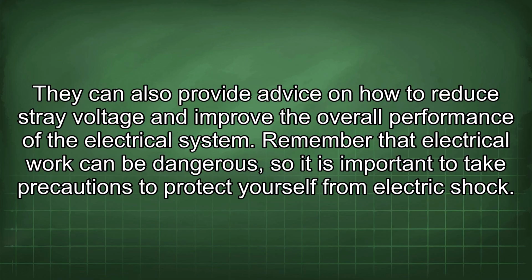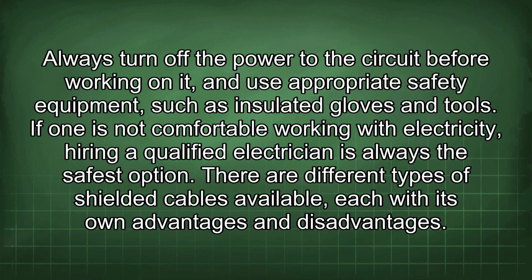Remember that electrical work can be dangerous, so it is important to take precautions to protect yourself from electric shock. Always turn off the power to the circuit before working on it and use appropriate safety equipment such as insulated gloves and tools. If one is not comfortable working with electricity, hiring a qualified electrician is always the safest option.